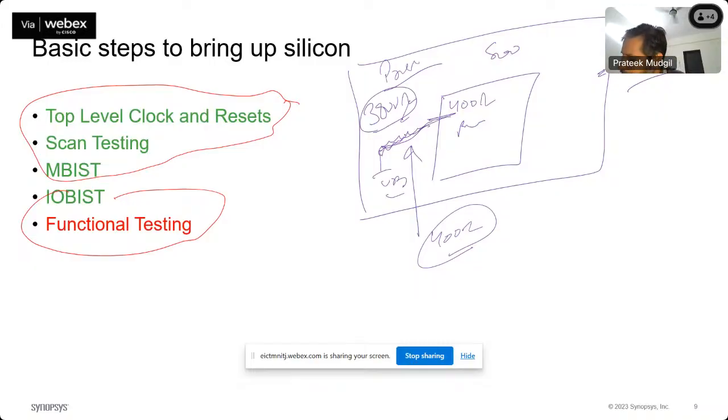So we checked it, we read the spec many times and said, okay, impedance is not an issue, everything is fine. So we were facing like a 1 month delay. Suddenly one of our seniors came, at that time I was very junior, and said, okay, bring your multimeter. That person brought a multimeter and asked the tester team to check the resistance. And we got 380 ohm, again a dummy number. Oh, this tester company has given us a tester board which has the wrong resistance value, not as per the spec, right? And we were 1 month delayed.